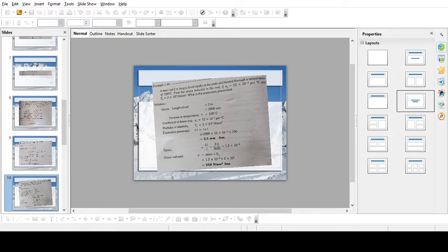Or also you can write alpha into t. Strain formula is alpha into t also. So it is also simply 12 into 10 to the power of minus 6 into 100. It will also give the same value, that is 1.2 into 10 to the power of minus 3.